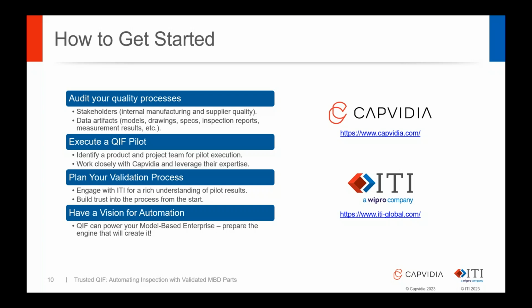Yeah, absolutely. Typically when you're validating QIF information, you're looking at more than geometry. The geometry is checked to ensure it is accurate from the CAD system through the QIF model. But in addition, that data includes things like saved views, which display the GD&T and other elements, notes, dimensions, things like that.